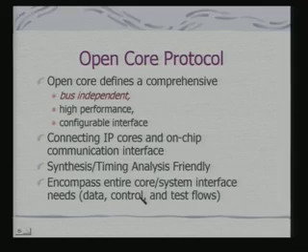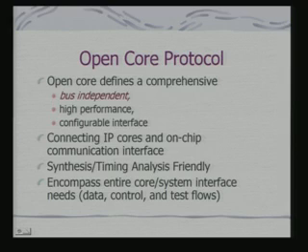The other trend which has developed related to buses for SOC is what is called the open core protocol. The example that we have seen so far is that of a particular bus, proposed, used and popularized by the ARM processor manufacturers. It has definite transaction definitions and specific signal definitions, and when you are designing an SOC, you pick up the modules compatible with this bus structure.